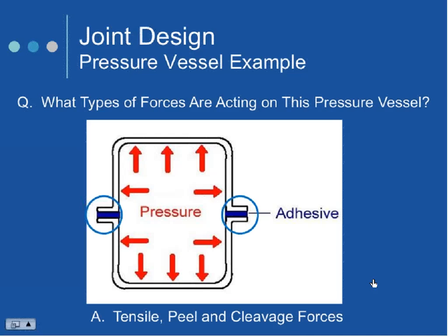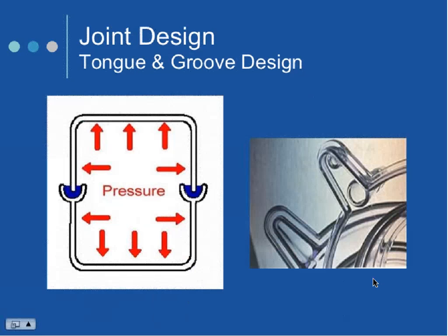And these are often made, I should have mentioned, of polycarbonate or acrylic thin film plastic that you want to move. So what we'd propose is, this is not a good, robust design. We'd want you to redesign that. And one that we would propose is a tongue and groove joint. Anybody here ever worked with a tongue and groove joint?